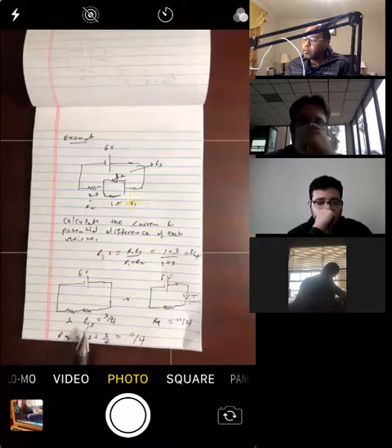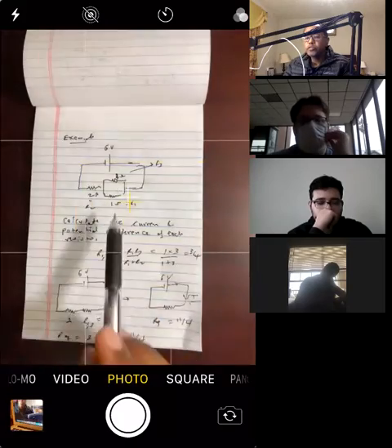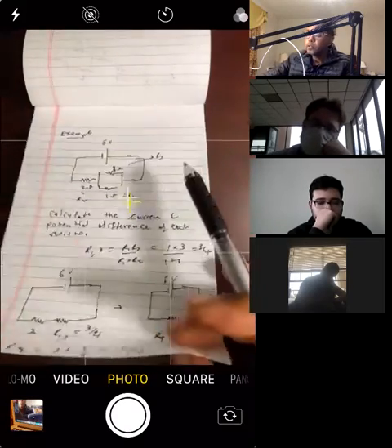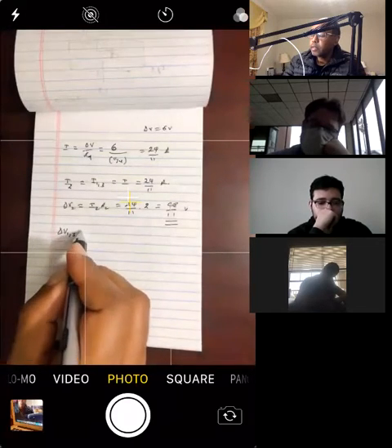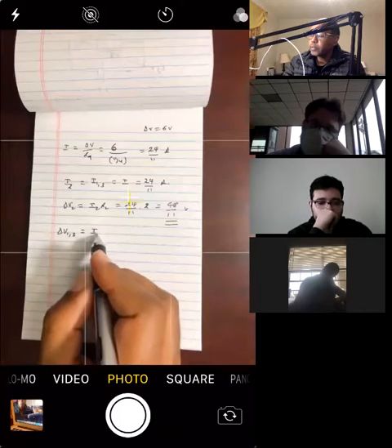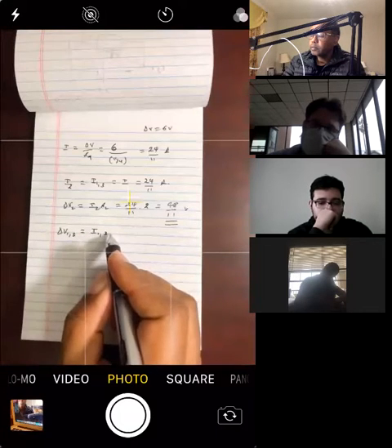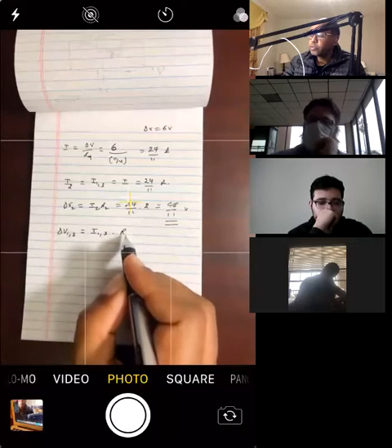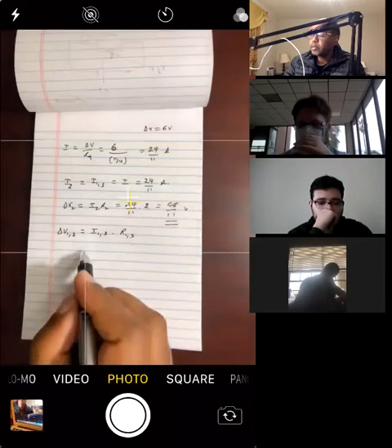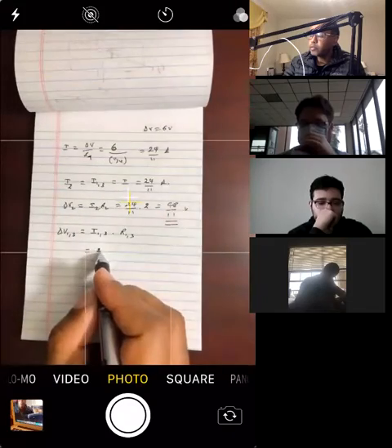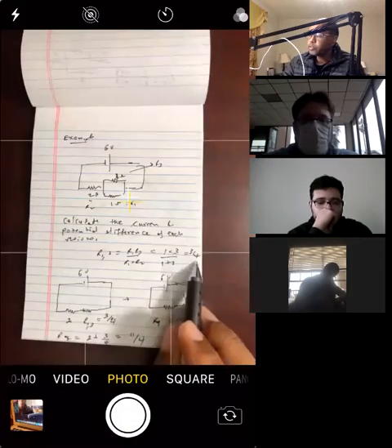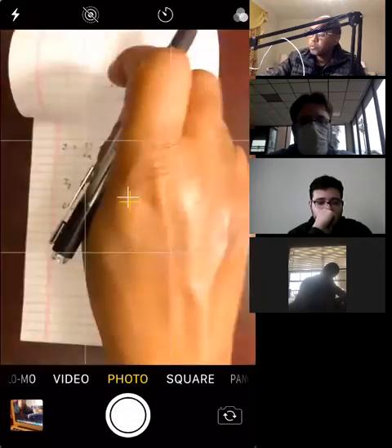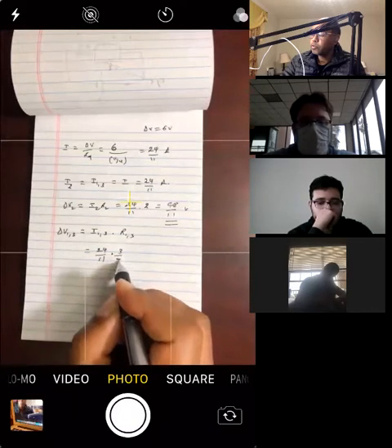Okay, let's calculate the potential difference across this one, because we know since these are connected, the potential differences are the same. Okay, so let's calculate the potential difference across the combination of 1 and 3. That is the current across 1 and 3 times the equivalent resistance of 1 and 3, right? The current is 24 over 11, so over here. What was the equivalent resistance for 1 and 3? This is the combination, which is 3 over 4, right? So this times 3 over 4, all right?